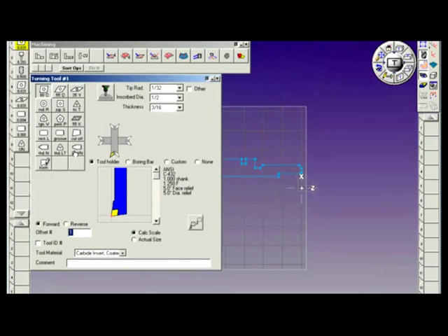As I've mentioned previously, some of you may not have seen it. We're starting with tool selection for facing and turning with this particular insert. This is an 80-degree diamond, and inserts are defined in categories: diamond inserts, 80-degree, 55-degree, 35-degree diamonds; the round, square, triangular inserts, trigon, pentagon, and the Kennametal lay-down style 55-degree roughing insert.